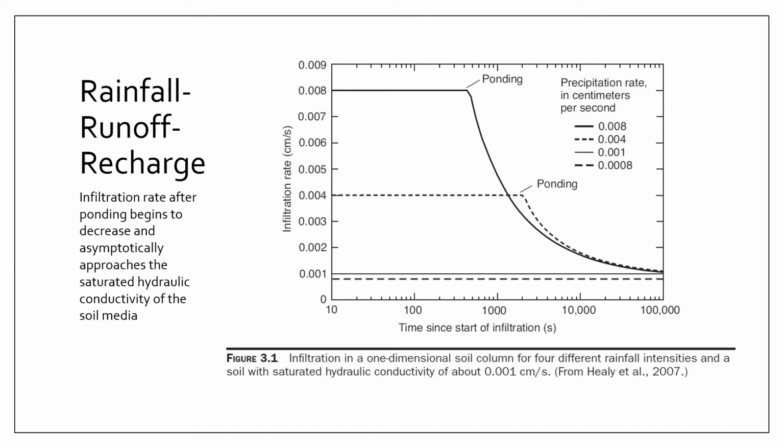Now what's happening here is you have your rainfall that's just spreading out and infiltrating and being stored inside the pores of your soil column. Okay, so the spreading of the rainfall and the storage is showing a rather fast infiltration rate until the soil gets fully saturated. Okay, once the soil gets fully saturated, it means that it doesn't have any more soil pore spaces for storage. Okay, and the infiltration rate will now be limited by the saturated hydraulic conductivity of your soil.